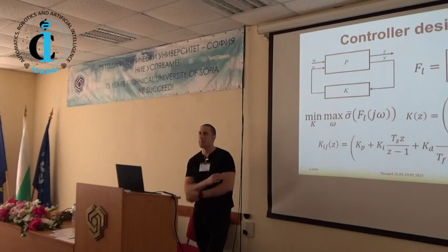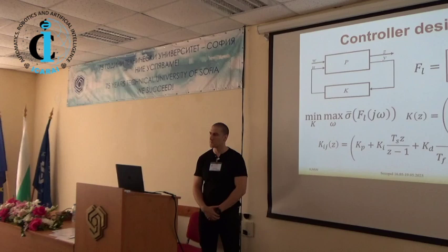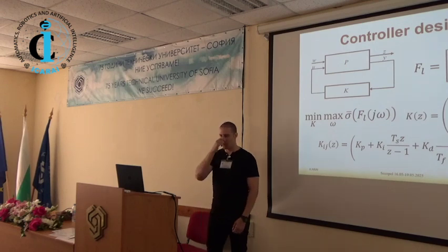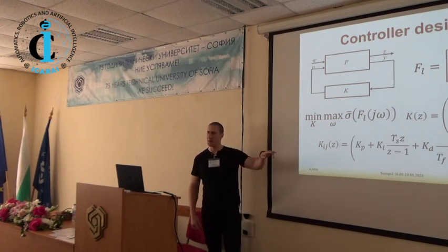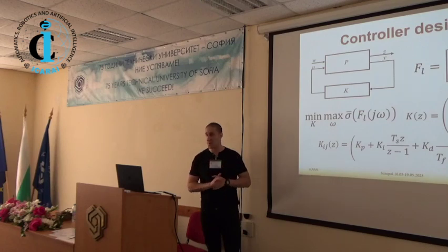And this is also applied, two years ago, in another function, even for mu synthesis, which is pretty new in MATLAB, but works very well for structured mu synthesis. For controllers with a given structure or at least a given order, which is practically the same. If we're talking about optimal controller, the gamma value for the H-infinity norm was around 2. So these controllers are obviously not optimal, but for this one we have kind of good performance.